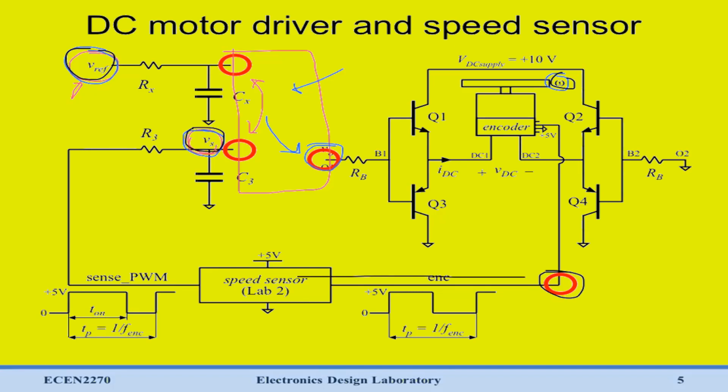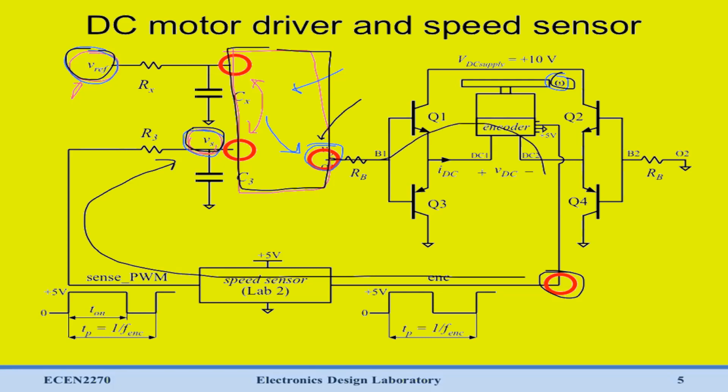So this is our speed sensor circuit, which takes omega to Vs. Next we'll look at our feedback controller, which takes the difference between Vref and Vs and generates a VO. And finally, we'll take a look at our motor driver and our motor and generate an equation which relates VO to omega. Once we have those 3 parts, that's the full loop.